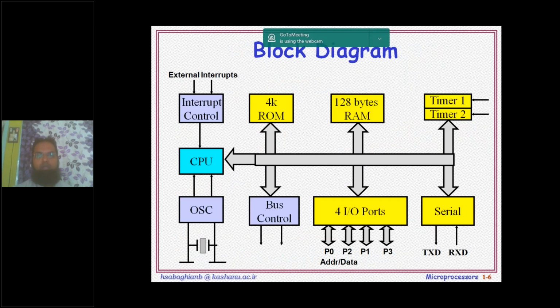These are memory locations. Now let us come to the block diagram of the 8051. The architecture of the 8051 is a little bit complex. If you cannot remember that architecture, at least remember this block diagram. This is the interrupt controller, this is the part of the microcontroller which acts as the CPU, this is the on-chip oscillator circuit, and this is a crystal which is connected external to the 8051 microcontroller.